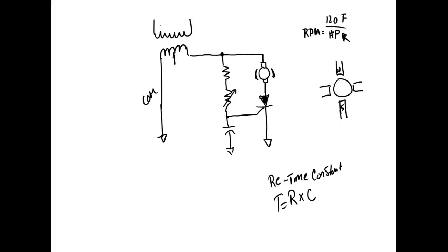So that means, okay, if I want to change the speed electronically, then we're going to play around with the frequency, right? You understand that? But the problem is, in AC, we learned a formula where X of L is equal to 2 pi FL. Well, see, now we've got two problems. If I lower the frequency, the X of L does what? Goes down. And now the motor's going to pull more current. If I raise the frequency, then now my X of L goes up and the motor may stall.